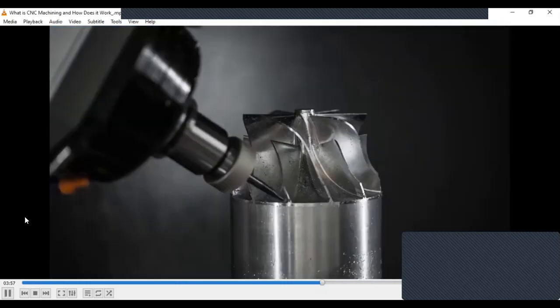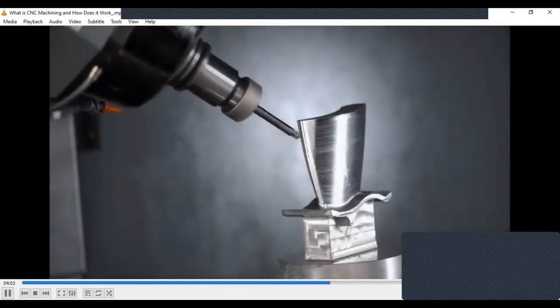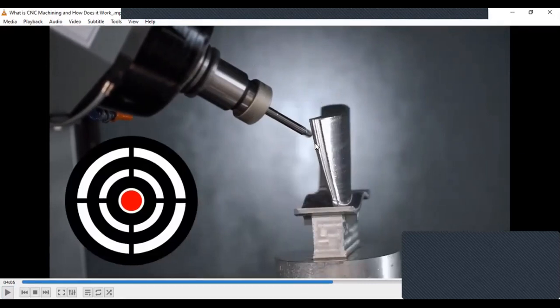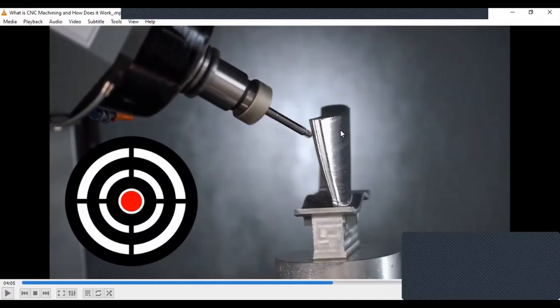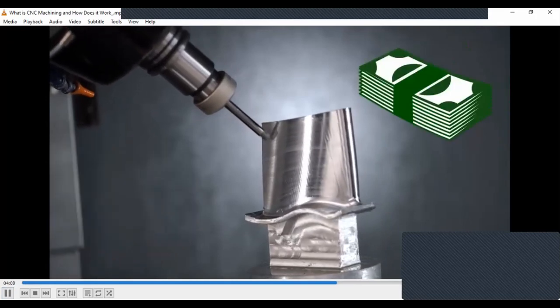As you might be able to imagine, the possibilities of production with 5-axis machines are practically endless. 5-axis machines used to be relegated to hyper-precision work, but as they have become more affordable, they are quickly becoming standard in many shops. You see how that is rotating as well? That's what we were talking about. That's rotation about one axis, or if it is moving like this, that's rotation about another axis. So that gives us the capability to machine these complex surfaces, right? To be able to form these surfaces which have complicated curves, and not just in one direction but multi-directional.